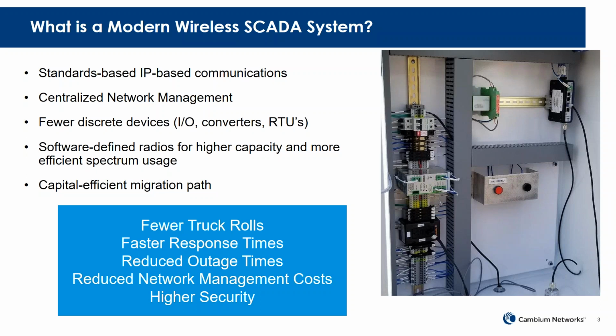There are fewer devices. In the upper right, you'll see sensors coming in to the radio itself, and that blue box is the cnReach radio. Coming into the top of that are the direct general purpose I/O connections. I'll talk about those in a bit more detail, but because this is a fairly simple tank monitoring application, they were able to eliminate an external RTU.